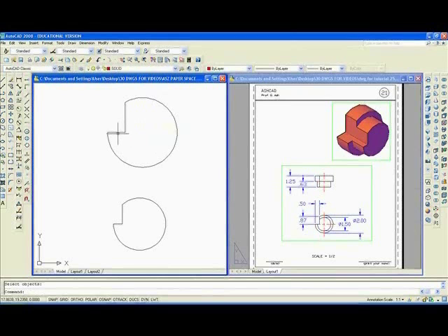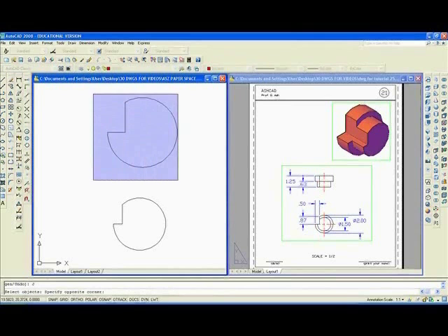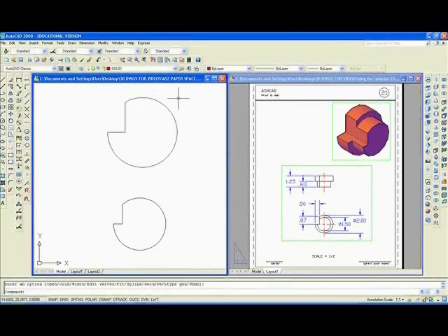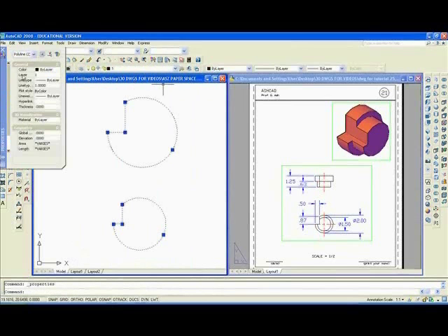So now what we have to do is convert them into polylines. I'll type PE enter, select a line, want to make it a polyline, yes, J to join, make a window. Now it's all one continuous polyline. PE enter, do the same here. Make it a polyline, yes, J enter to join. And I suppose we really want to select it all and place it on layer, not one, but solid. Should turn red.